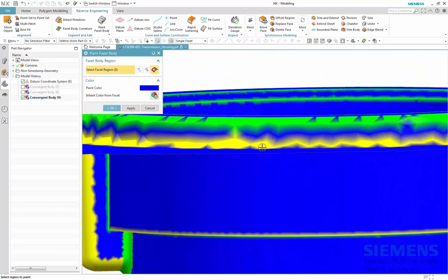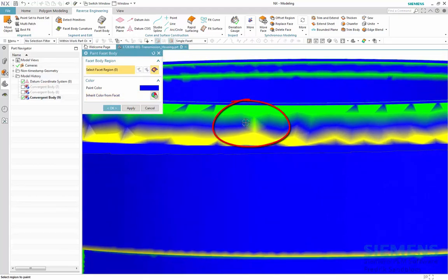We could continue by trying to refine the threshold values for the facet body curvature color coding. However, this might be a bit time-consuming, so we choose an additional option to directly set the color coding so that we get the precise result that we are expecting.